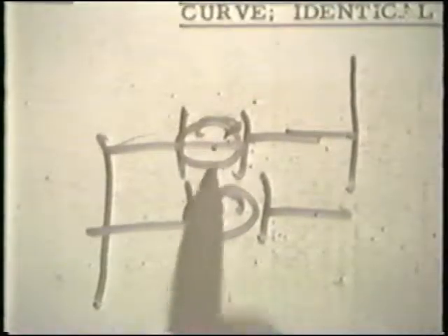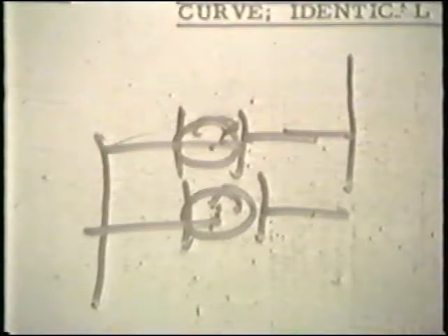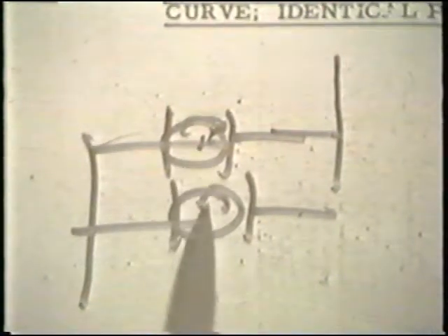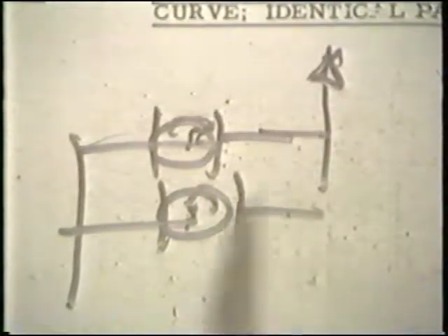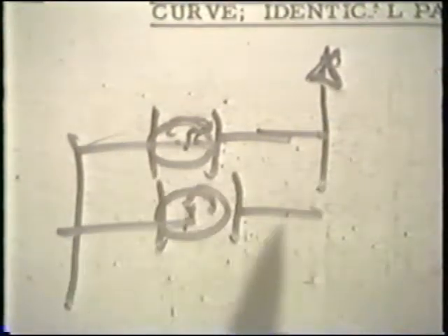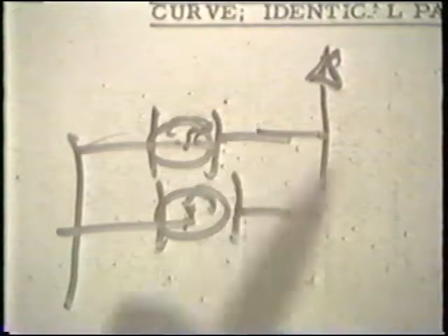So we can start out by noting that if pumps are in parallel application, each pump must provide 1/2 the flow rate delivered to the system, and that each pump must operate at the same head.